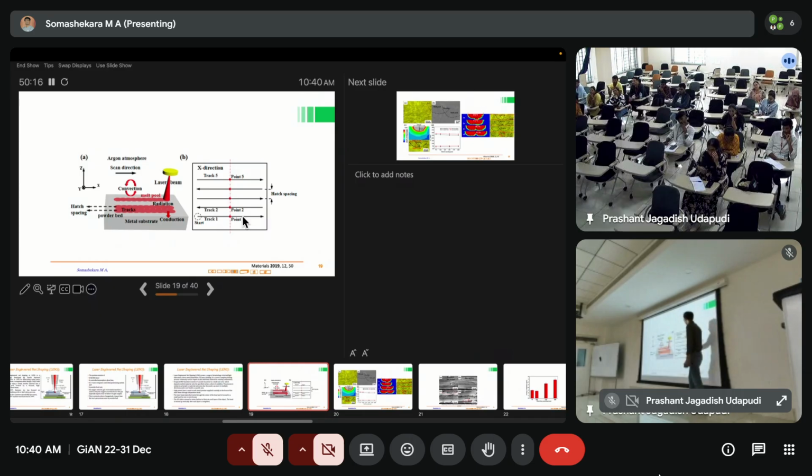Now, since you are generating a lot of heat, how are you maintaining your plate without warpage, without thermal differences? You also need to make the heating uniform every time you do path planning. Otherwise, in one place you have the melt pool, and in another area you may have a fully solid structure, which ends up forming a lot of residual stress.